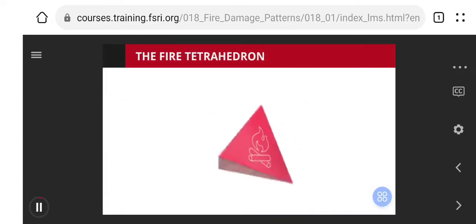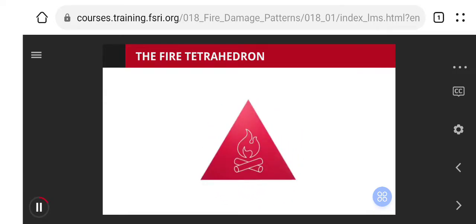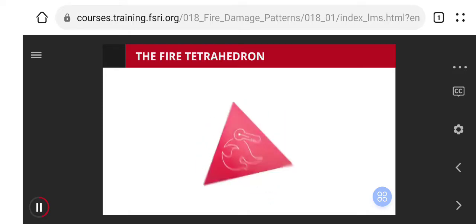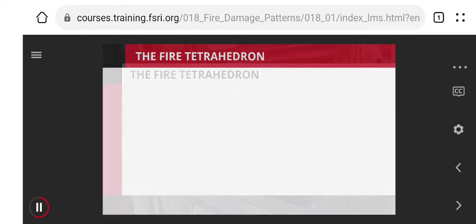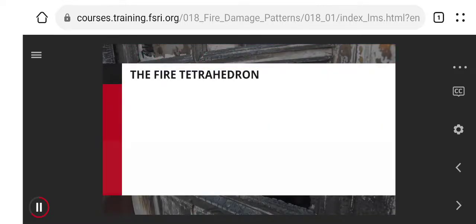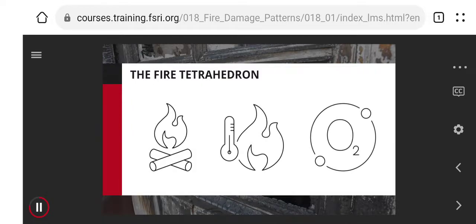In the simplest terms, fire needs four elements to exist: fuel or combustible material, oxygen to sustain combustion, and enough heat to pyrolyze the material to raise the gases to their ignition temperature. Subsequently, an exothermic chemical reaction is needed to sustain flaming combustion. As a fire investigator, if you can determine where and when the three essential components of fuel, heat, and oxygen are available to react and support flaming combustion, you will have some ability to understand the movement of a fire through a structure.